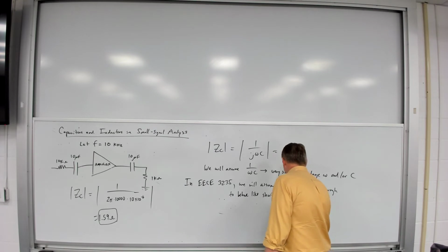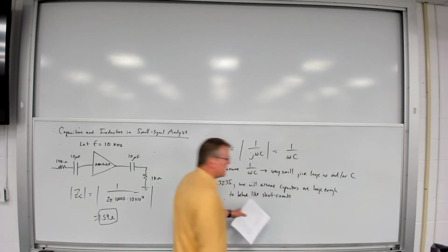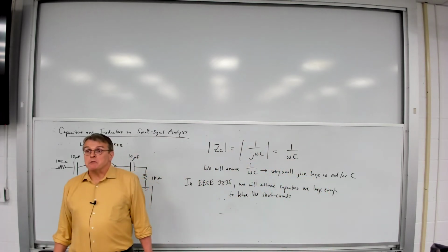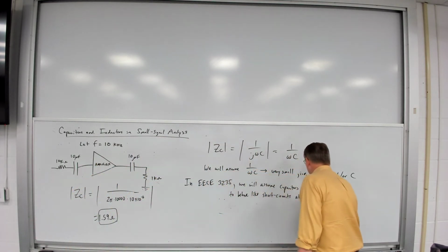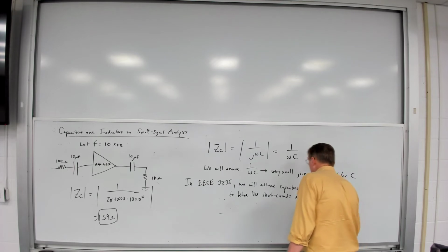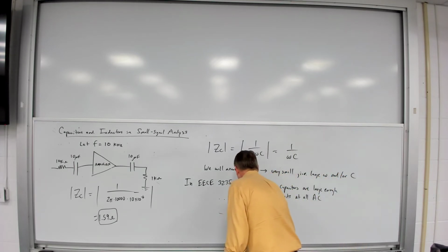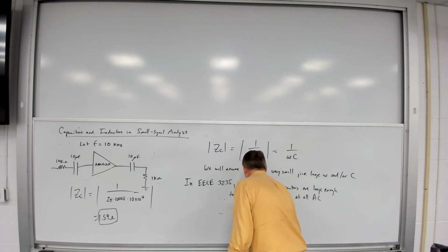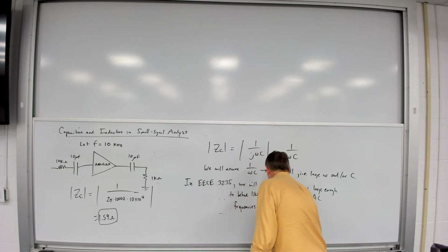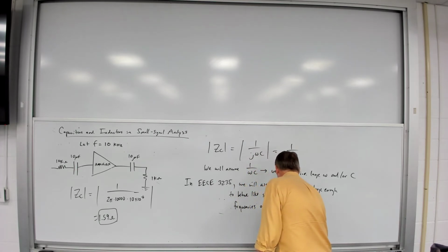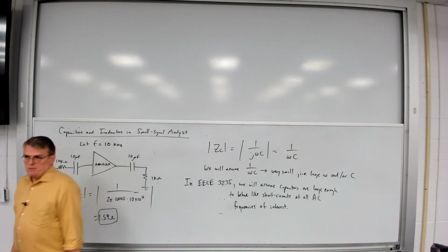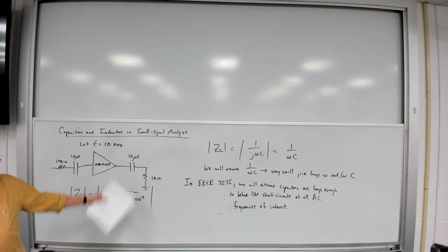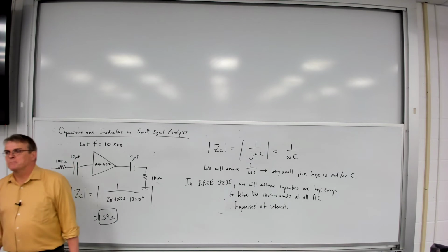So the capacitors will act like short circuits at all frequencies of interest, at any AC frequency we care about. So we're going to make it easy on ourselves. We're going to assume capacitors act like short circuits.